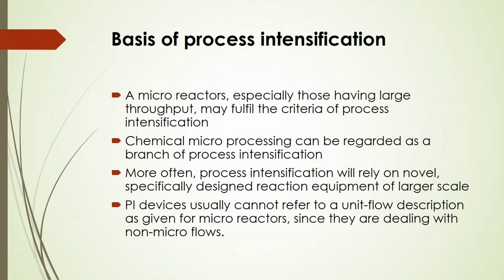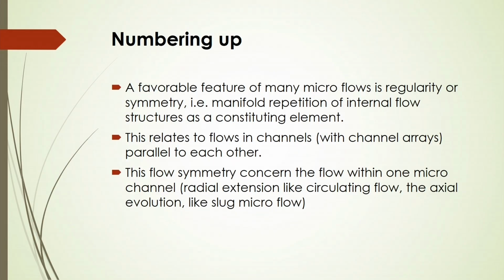Also you can say that process intensification will rely on novel, specially designed reaction equipment of the larger scale. Now, in this regard it is very important, whenever you are going to apply this microprocess technology by developing a process intensified device, to think that using just a single channel will not be economic, or will not be a large scale application. So you have to think about the numbering of channels.